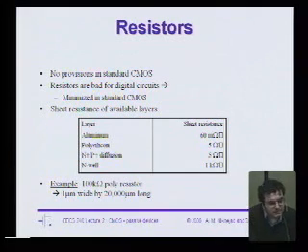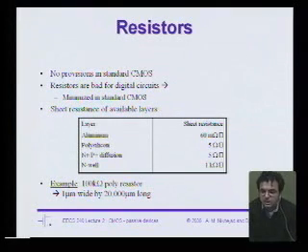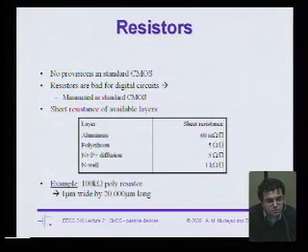Yes? Silicide? That's right. So most modern processes use silicides in the source and drain junctions, and as a consequence, the gate. And so the polysilicon resistance is actually much lower. And we'll talk about ways of blocking that to get a better resistor. It's actually a process option.